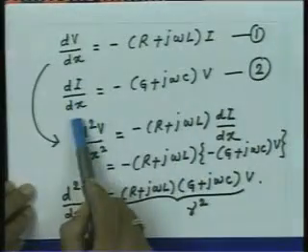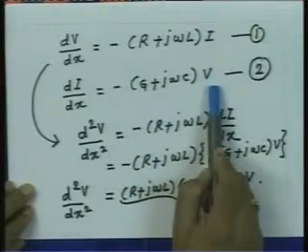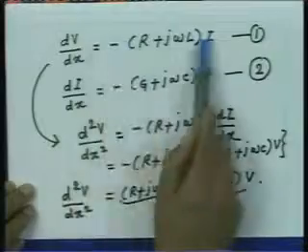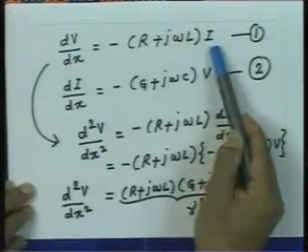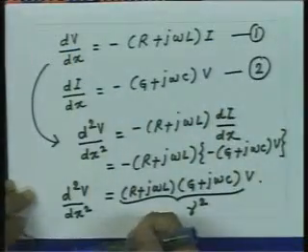So, first thing I should notice is that the voltage and current expressions which I have written are completely general in nature. That means they must satisfy the original differential equation at every point on the transmission line. So, first thing I can do is take this voltage and current and substitute into the original differential equation. If you recall, we had dV by dx equal to minus (r plus j omega L) into I, and dI by dx equal to minus (g plus j omega C) into V. Now, I know the expressions for V and I. So, I can take any of these two equations and substitute the general expressions for V and I in this, and then try to establish the relationship between the arbitrary constants.